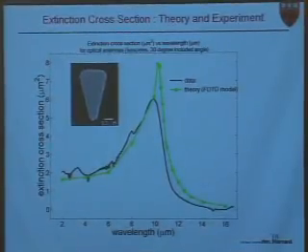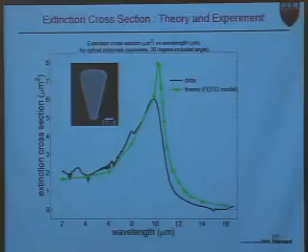So this cross-section has units of area. When multiplied by the intensity of the input illumination, which is in watts per meter squared, it gives a power. And this represents the power that's removed or extinguished from the incident beam by the antenna through the process of scattering and absorption. It's equal to the sum of the scattering and absorption cross-sections.